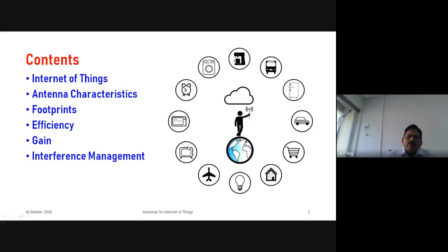So here, for the base station, if you are able to have a tower with an antenna array, where you can control the amplitude and phase of each antenna element, and you are able to make a null towards the direction of this object, this wireless system which is creating interference for you, so that if you are able to orient the null in this direction, then minimum interfering signal will reach this antenna and be able to disturb you.